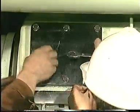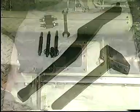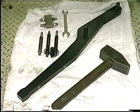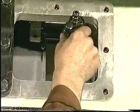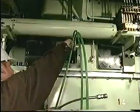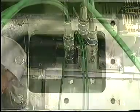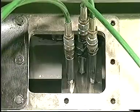If the camshaft has been dismantled or if new cams have been mounted, adjust the cams before mounting the lower part of the camshaft housing. Remove the plugs from the cam and insert copper gaskets. Mount, but do not tighten the snap-on couplings. Connect the snap-on couplings to the high-pressure pump and vent the system. When oil without air bubbles flows from the couplings, fully tighten the couplings.